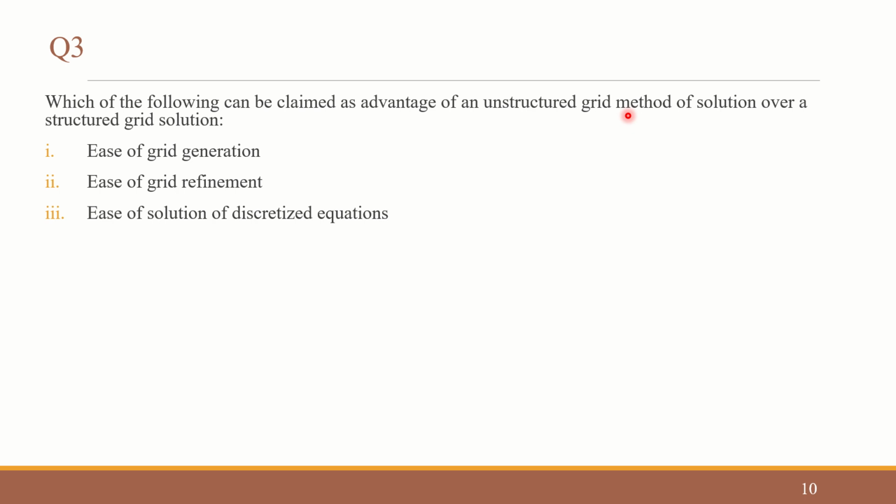Ease of solution of discretized equations. But when we talk about structured grid and unstructured grid, if we have the same kind of geometry for both the cases, we will get the solution better in structured grid than unstructured grid. So therefore we cannot say that solution will be easier obtained using unstructured grid. If that is the case, we can go with all geometrical problems using unstructured grid only, because it is having certain advantages as well as